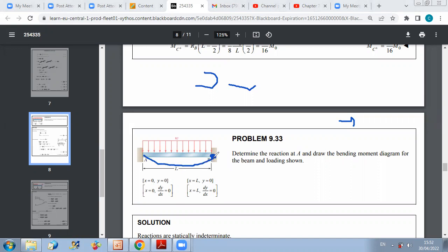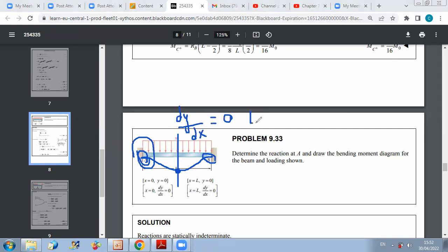And the value of the reaction is the value at B. If you want to illustrate it accurately, we have a slope 0 here. So the deflection slope is 0, it's like this, and then it's like this. So you have a symmetrical deflection curve, and conditions at A are similar to conditions at B. This is why it was only needed to use relations at A because of symmetry, and to use the maximum deflection at the middle, which also gave us an additional equation, dy by dx is 0 at L over 2, to close our system of unknowns. Okay.